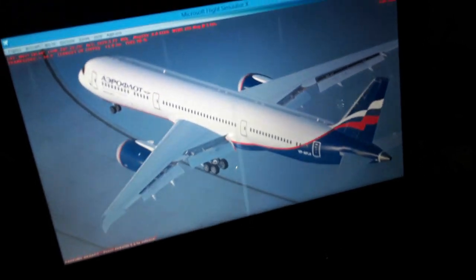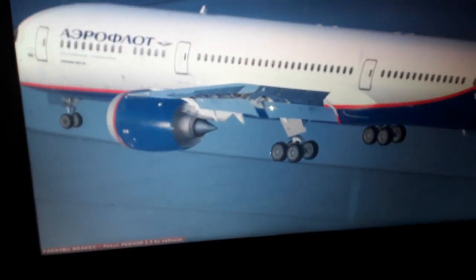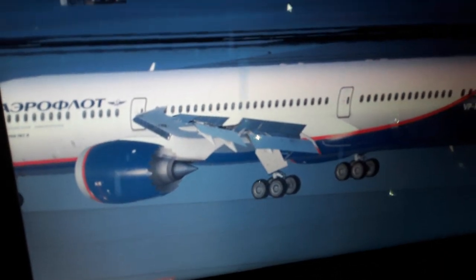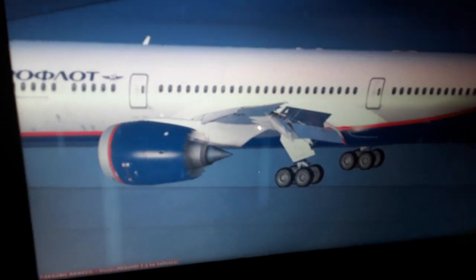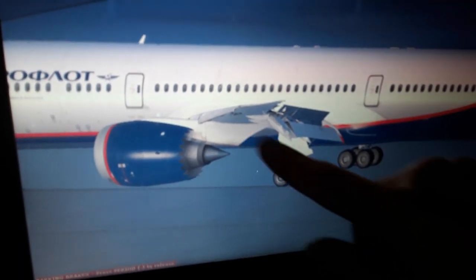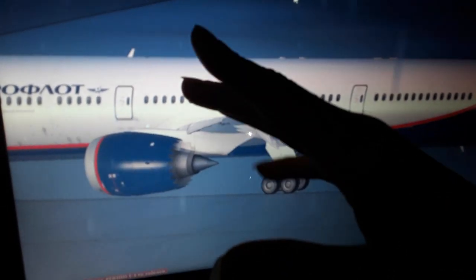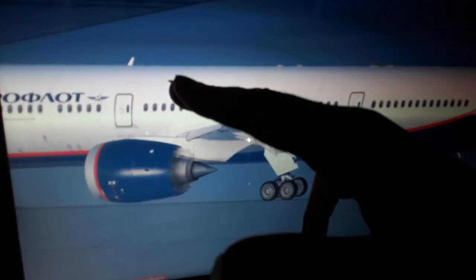So you can see also the wings. You can see the bottom surface of the wings is more flat, using fluid mechanics and Newton's physics. You can see as we fly for takeoff, the airflow is moving slower below the wings, so we have higher pressure. Also the flaps are extended and we take an angle of attack like this for takeoff.